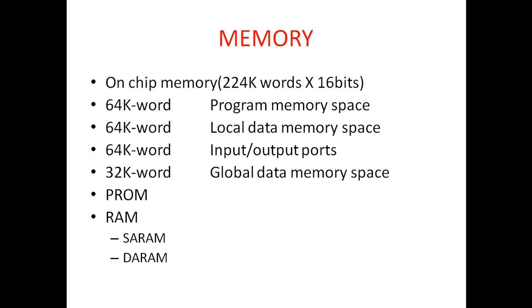On-chip memories of 224 kilo word length of 16-bit length: 64 kilo word of program memory space, 64 kilo word of local data memory space, 64 kilo word of input output port and 32 kilo word of global data memory space.